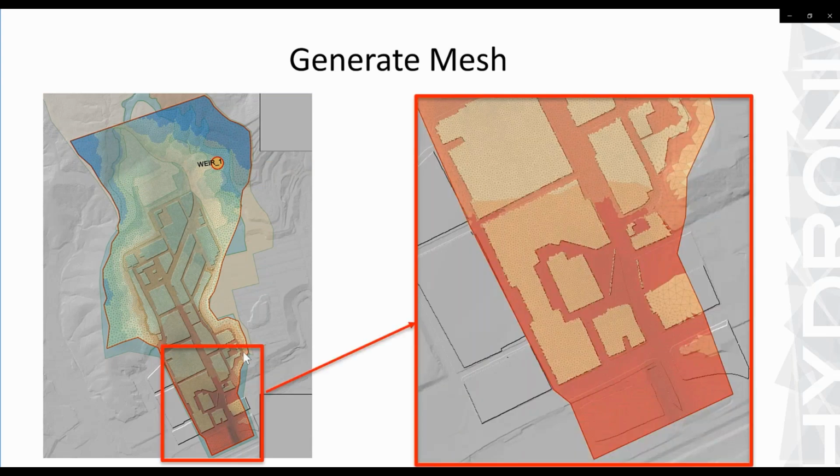So the other thing that I wanted to show you is that the mesh is fine enough to capture many of the features of the terrain and urban area. As you can see here, we have some features in the terrain that are accounted for with a flexible mesh. One of the advantages of the flexible mesh is that you can have break lines that force the mesh to adapt to all these complex features, and that's very convenient in many applications.